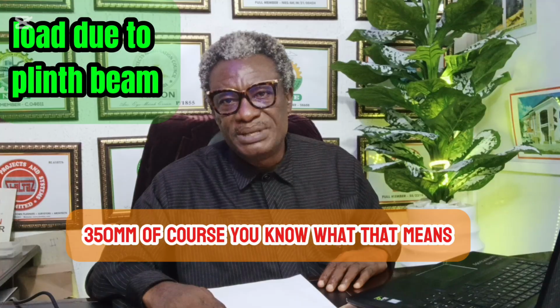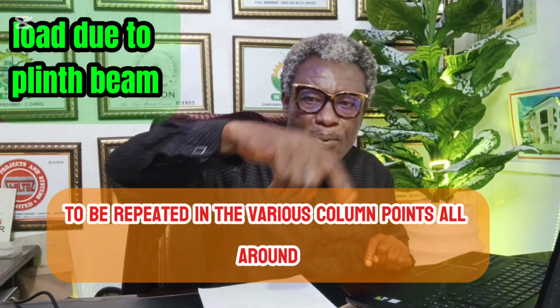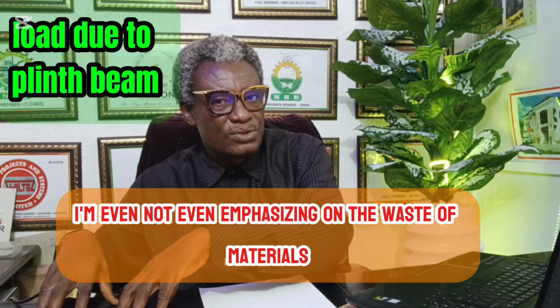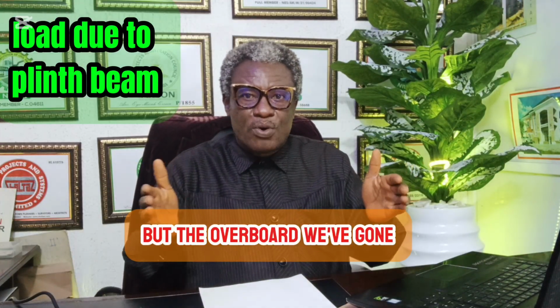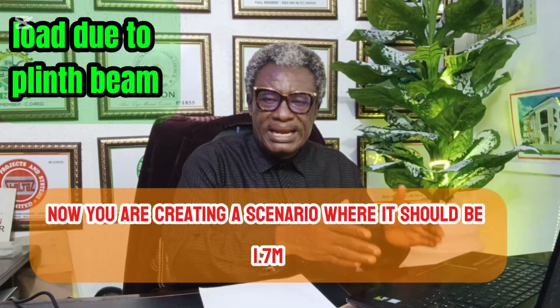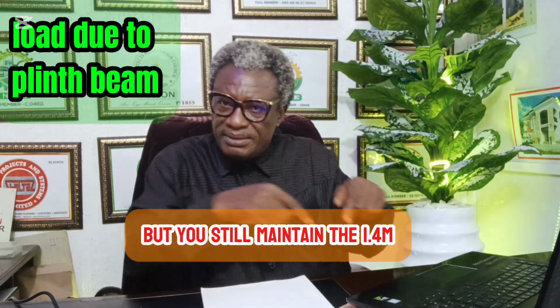Of course, you know what that means, it is to be repeated in the various column points all around. You can see what that can cause. I'm not even emphasizing the waste of materials, that is not the concern, but how overboard we've gone. The design by the engineer said 1.4. Now you're creating a scenario where it should be 1.7, but you still maintain the 1.4.